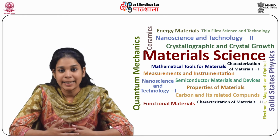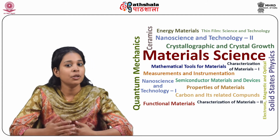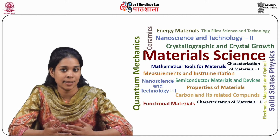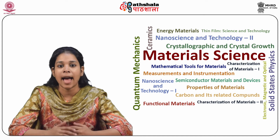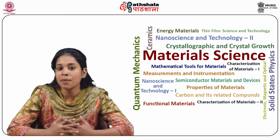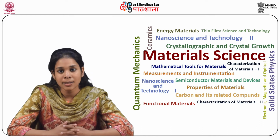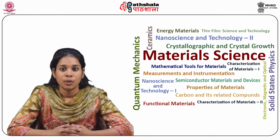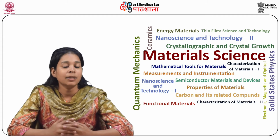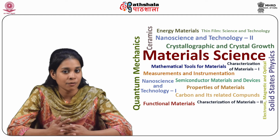However, graphite can be used only in an inert or reducing atmosphere. The use of pressure makes it possible to achieve nearly full density with a fine grain size and at lower temperatures. It is possible to sinter some composites which cannot be sintered by pressureless sintering, such as Al2O3, silicon carbide, etc. composites, but the process is expensive and is used only when the additional cost is justified.